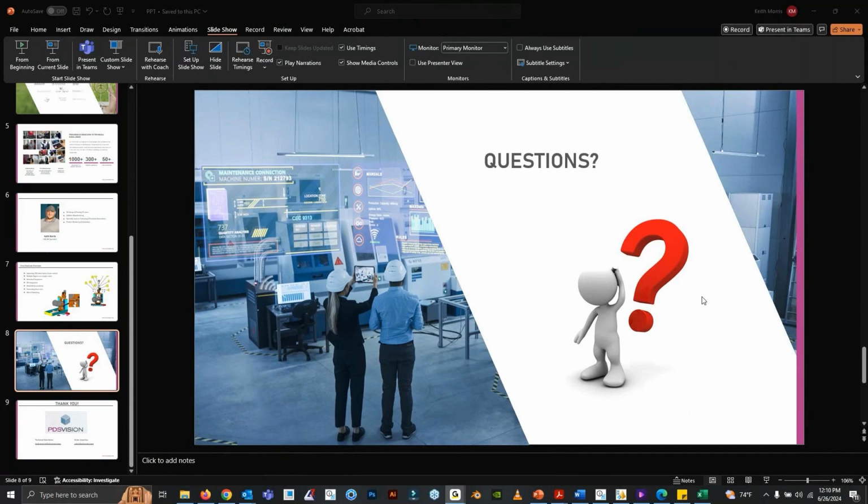Sarah, I believe you're asking about setting up a camera so we can fly through the animation, and it would have sort of this 360 view, like a rotation almost. You could definitely animate the camera to do that. I was just animating the components, but yes, you can do a fly-through. You can animate a camera within Creo Illustrate to achieve that effect.